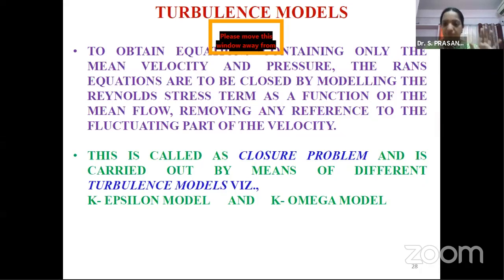Among the two equation models, the K epsilon model and the K omega model are adopted very widely, because they are easy for analysis, and they give you maximum information about the velocity and pressure parameters or any properties you want to evaluate for a particular case study in a particular domain of boundary condition or control volume.